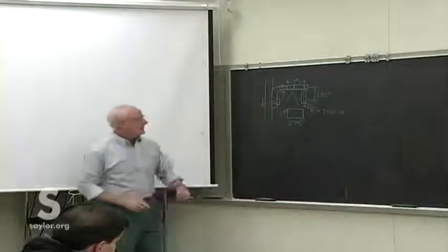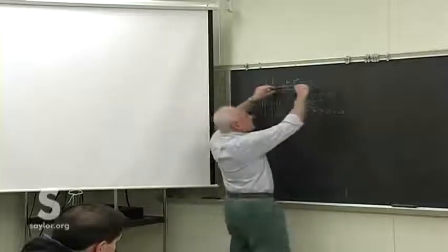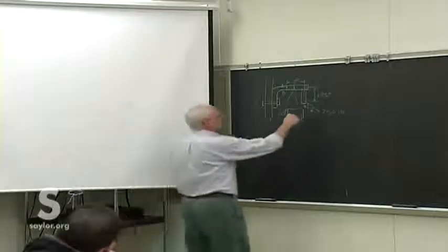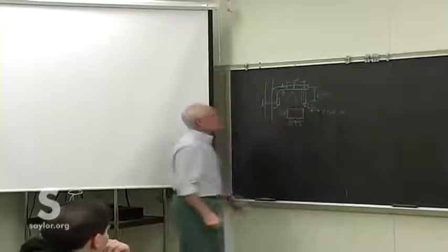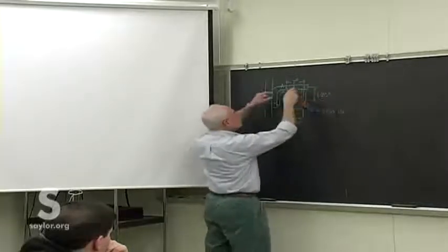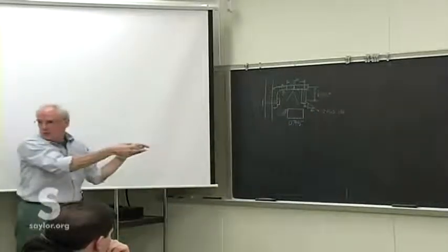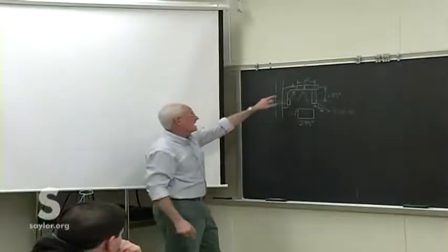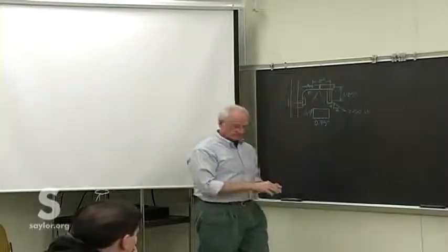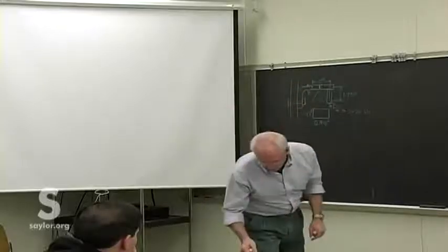So what we're going to get is some axial force due to the horizontal component of this that's trying to pull this bracket in an X direction, if you will. Then we also have some bending component due to both of those components. Both the horizontal component is trying to bend it one way, the vertical component is trying to bend it the other way. Whichever one of those is dominant tells us which direction the bending is there, but we need to add that stress to the axial stress that we're also feeling.